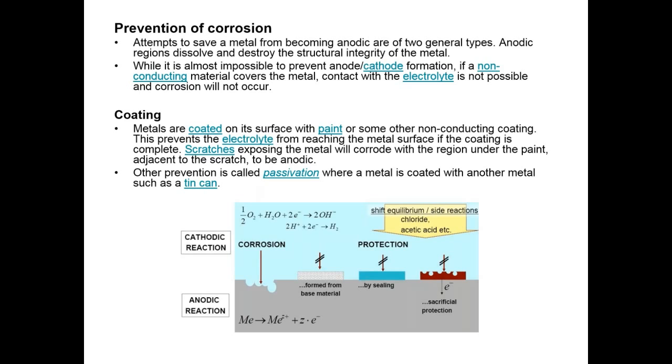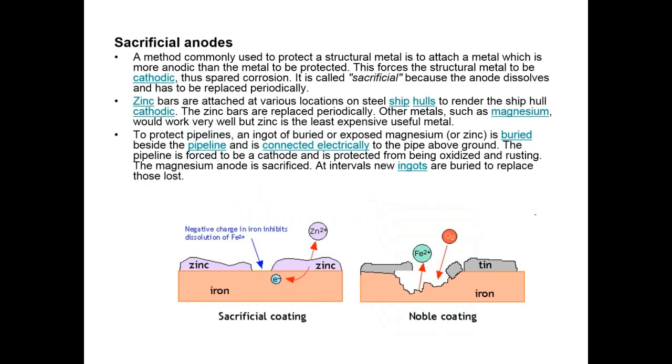What I'm talking about are anti-corrosion additives that can be actively generated to form a thin film during the mechanism of corrosion. A simple one to talk about is sacrificial anodes. A good example is zinc. Zinc, as you can see here, has a higher oxidation potential. So if you look at the EMF value as shown earlier, zinc will be oxidized first before iron. Thus, zinc as an oxidized material will transport electrons to iron, and hence it will eventually be consumed.